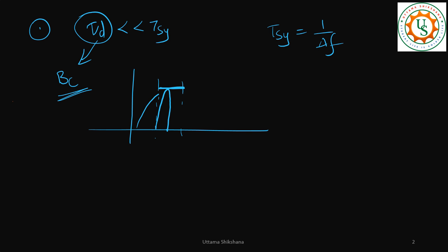It should not be more than this. Then for this entire width of the subcarrier, the channel is not flat, right? If you consider this much is the flatness, our subcarrier width should be taken in such a way that it experiences the flatness of the channel.